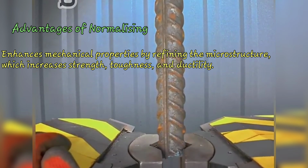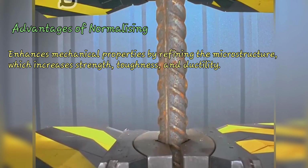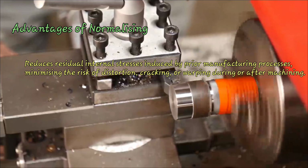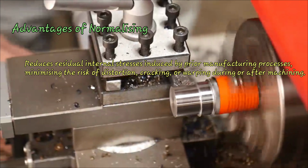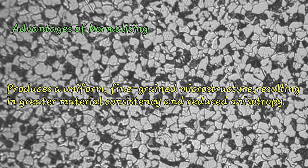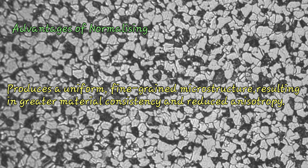Advantages of normalizing. 1. Enhances mechanical properties by refining the microstructure, which increases strength, toughness, and ductility. 2. Reduces residual internal stresses induced by prior manufacturing processes, minimizing the risk of distortion, cracking, or warping during or after machining. 3. Produces a uniform, fine-grained microstructure, resulting in greater material consistency and reduced anisotropy.